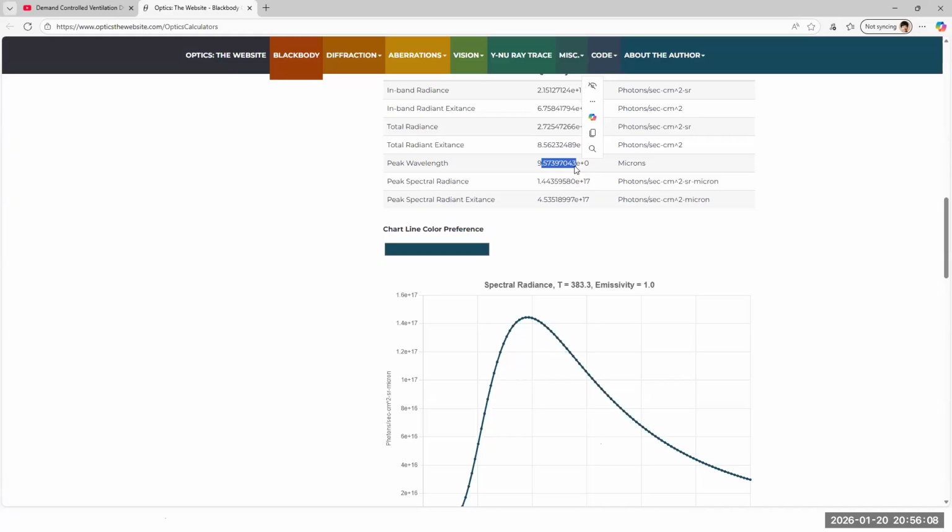So now we understand that the thermal radiation spectrum of black body objects at these temperatures, although it shifts, has its peak mainly in the atmospheric window. This is for an object with thermal emissivity 0.1. Unfortunately, most building materials have low thermal emissivity, especially from 8 to 13 micrometer.